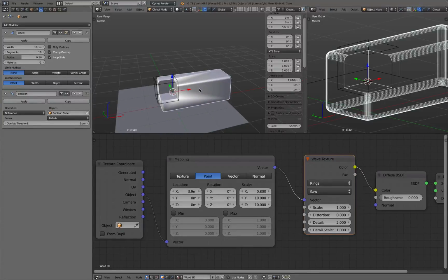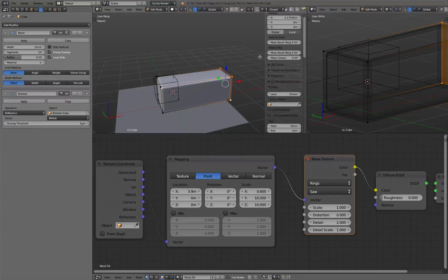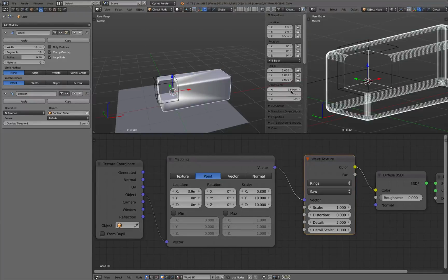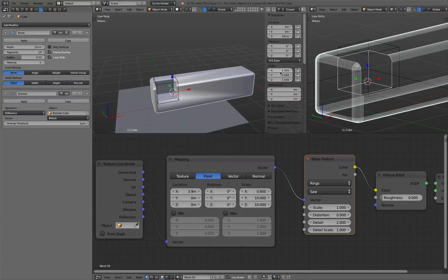There's another way we could do in object mode. This only works in object mode, not in edit mode. You see in edit mode you have different settings for transformation, and in object mode we also see the dimension. Now in dimension we can see that X currently is 2.6 meters. Let's say we make this 4 meters. And one thing is very important. You see there's a scale factor, because in object mode we adjusted the dimension, and that adjusts the scale. And this scale factor will influence the dimensions and values we have in mapping.